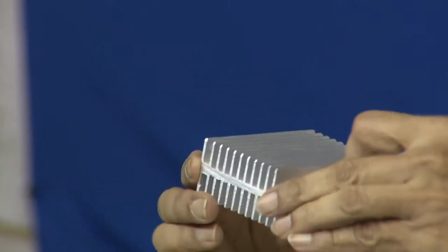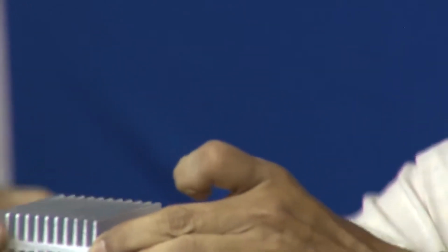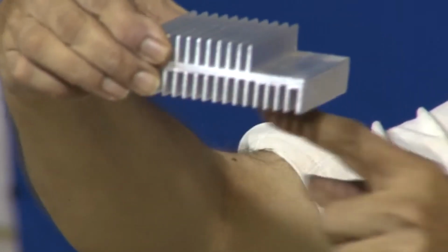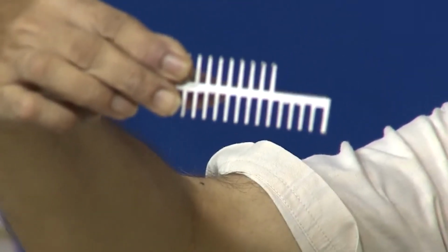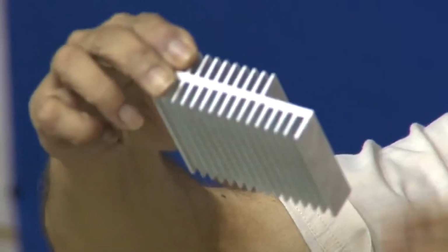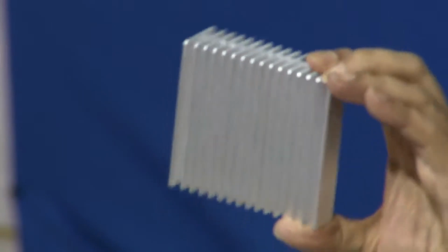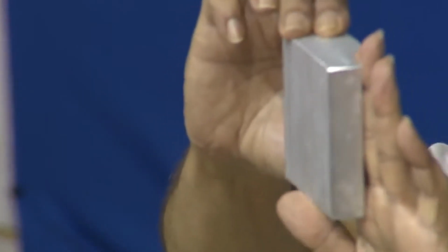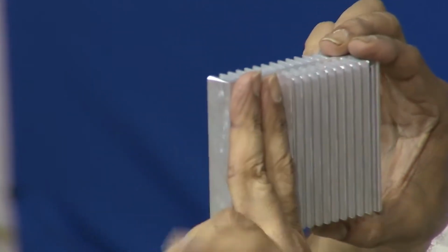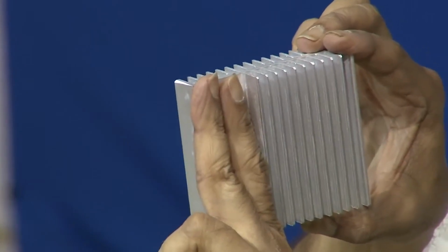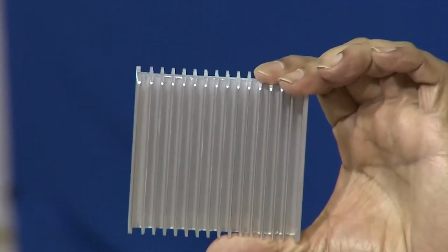So, if you mount a power dissipating component here, it does not look intuitive that the one in the bottom, I doubt whether it actually can do any good at all. You have seen this, no? So, obviously, for such a thing there is only one way to mount, vertical, and in vertical again we need to provide some sort of a cover over this, and then after that it neatly just sits there like that.